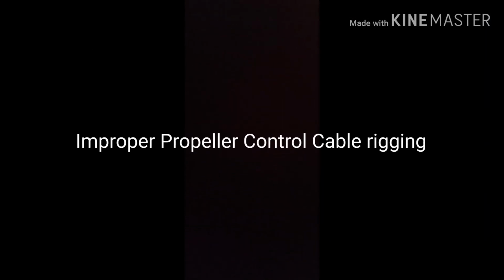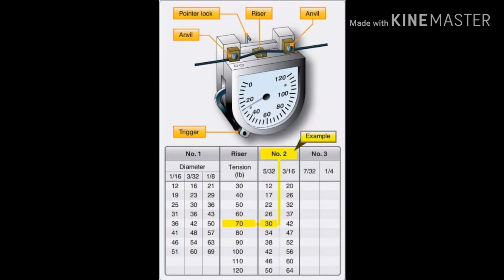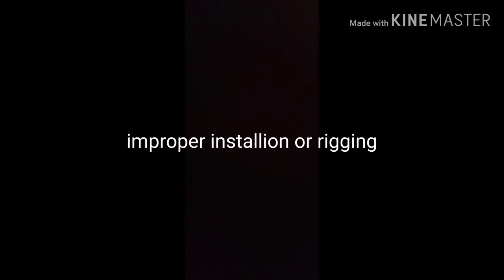Next is improper propeller control cable rigging. The propeller control cable must be installed and rigged to allow the full governor range to be selected from the propeller control. If the cable is too short, the low pitch high RPM setting may not be achieved. If it is too long, the feather stop may not be reached, preventing feathering. The cause is improper installation or rigging.